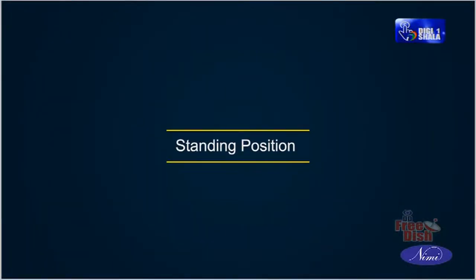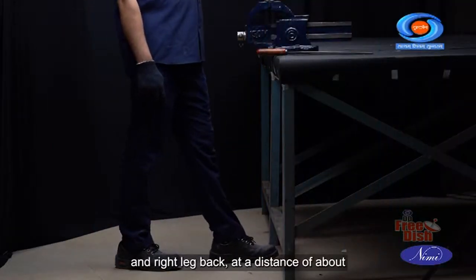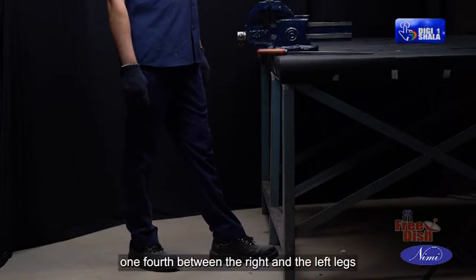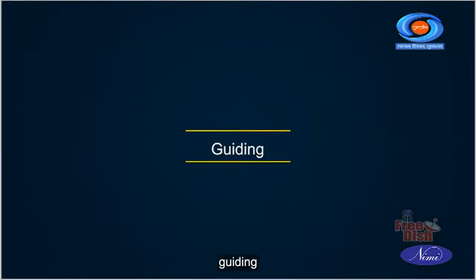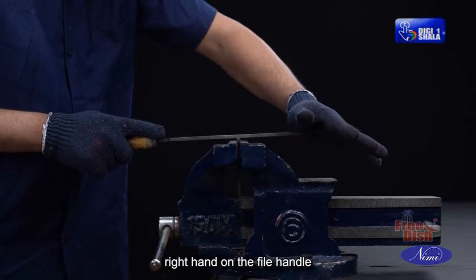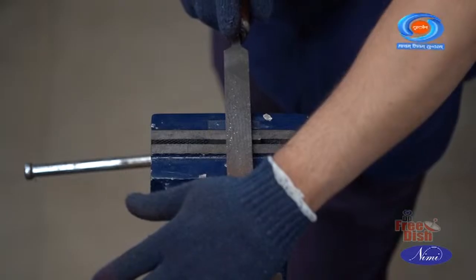Standing position. Left leg in front and right leg back at a distance of about 1 foot between the right and the left legs. Guiding. Right hand on the file handle and left hand on the top of the file face.